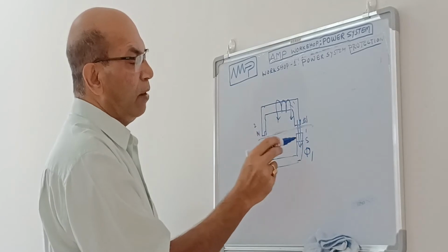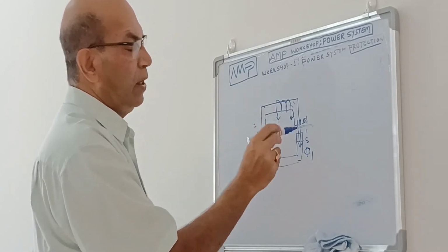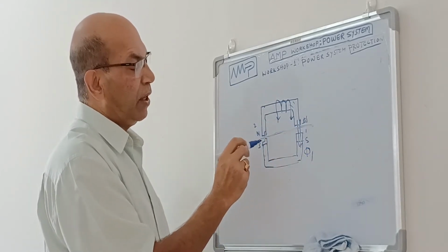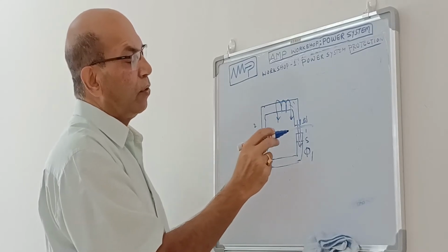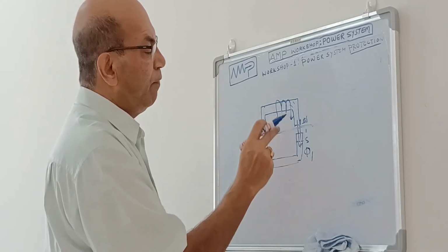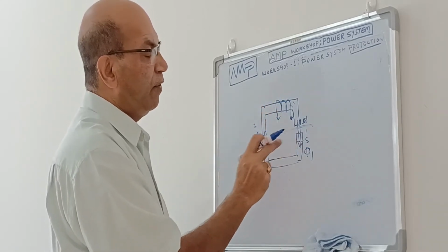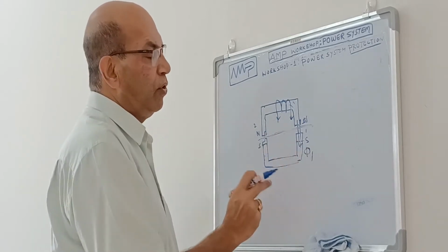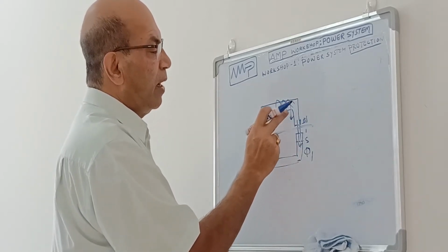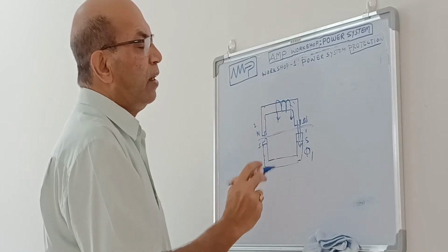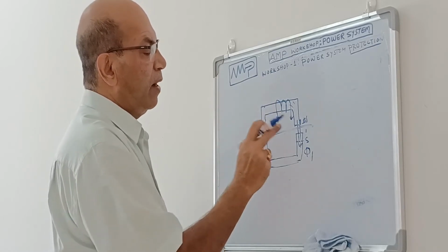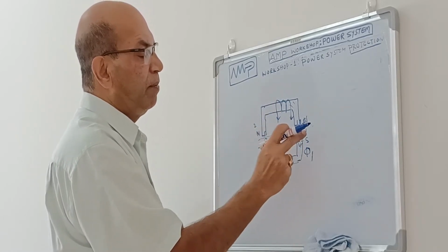And now you see these two poles are not identical. Here the pole is a split type, called a split pole. So why have we made this pole? To make the magnetic flux differ in phase between these two. This is an AC supply, so the magnetic flux is AC in nature. This AC magnetic flux we want to split so there is a phase difference between these two.